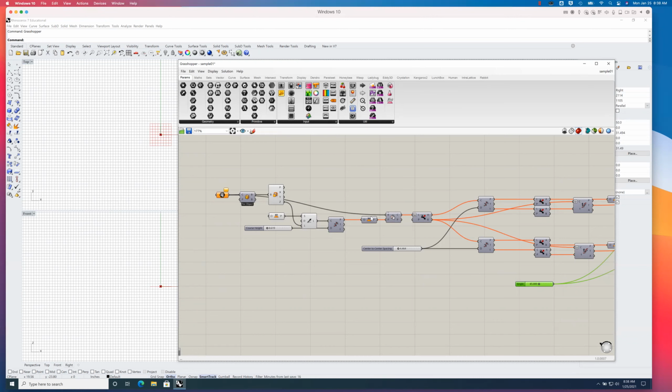And so a lot of the stuff that you've traditionally done manually when you're modeling something, here you're actually recording the process itself, the algorithm. And you can start to build in variables. So not only can you rotate something, but you can say, I'm going to build in a variable for how much rotation, in angles or radians, and how many times you rotate. Maybe that's a number. You can even make number sliders so that you can change those variables by simply sliding the number slider. Okay.